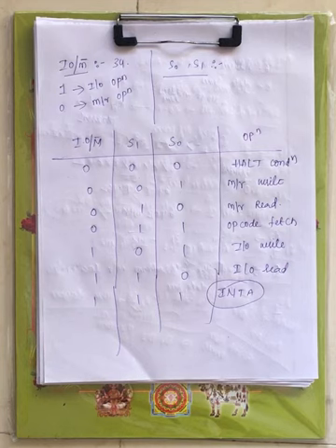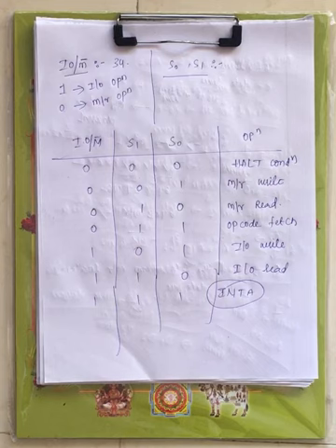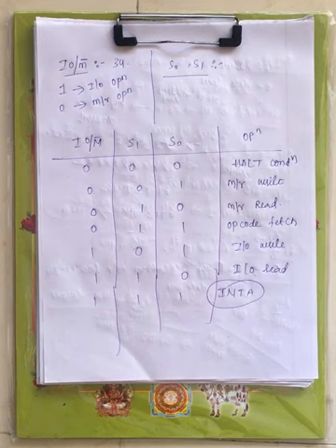Now when IO slash memory bar is 0, which indicates memory operation, when all are 0, it is halt condition. The microprocessor is under halt condition. When it is 0 0 1, that indicates memory write operation. When it is 0 1 0, memory read operation. When it is 0 1 1, opcode fetching, that is, we will fetch the opcode from the memory.